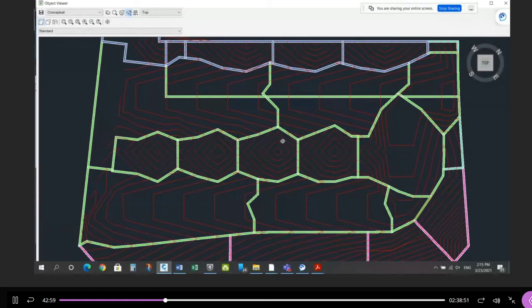These are the areas that delineate the drainage to each catch basin, and this is going toward the road. This is going toward the road, right? You can see the areas here, 1, 2, 3, 4, and the drainage divide. These go to the backyard, these go to the front yard, and so on. So I can quickly look at it in CAD, okay? But I have a sense of what the pattern is, so I only really need to look at the drainage patterns. So you can see how the high point or the split point defines the drainage divide between the front and the backyard. And then you'll also see where all the maintenance holes are.